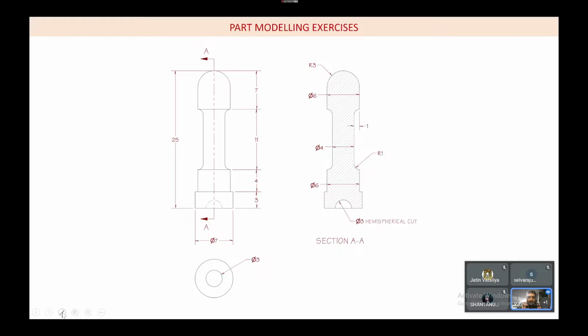So if you don't know, that is okay. What we are going to do is create some sketch like this, and we are going to revolve it about the axis. Or else you can draw your full semicircle also, that is not a problem. When I am going to revolve, I am going to choose the cut operation instead of the addition operation. Last time I told you there is something called Boolean operations. In that there is something called cut.